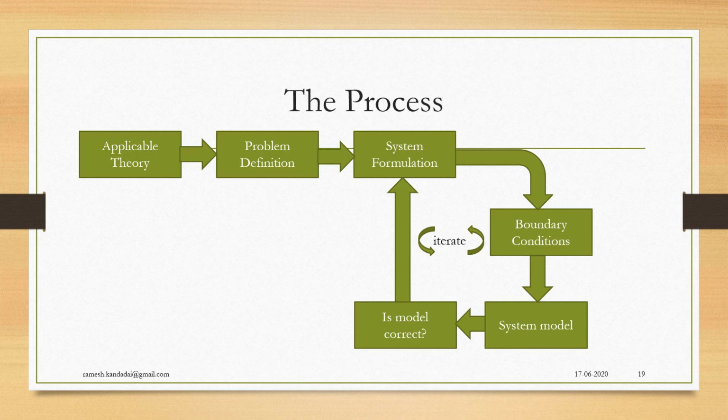Once you have assembled the model using any one of these two techniques or any other techniques that are possible, you look at the system model and see if the model is correct. You take into account for a particular input what is the analysis of its response. To do the analysis of response, there are many things involved. One of them is to use Laplace transform on the equations of motion to simplify the motion.